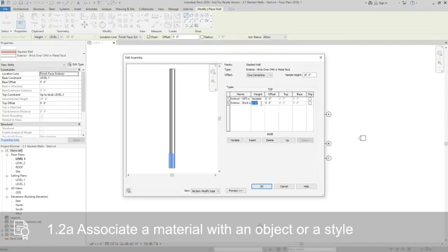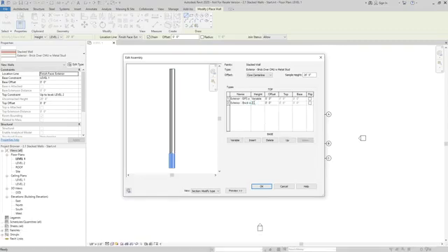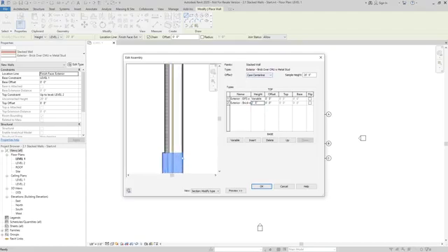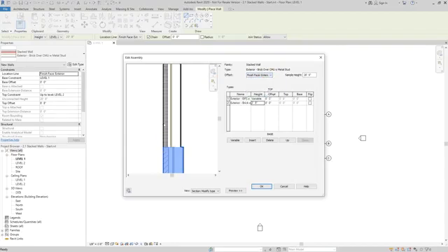For our base, we're going to set this to 2'8". And our offset, which is going to allow us to align the walls into different locations, we're going to set to finish face interior, because we want to make sure that this interior face is always aligned. The way the two walls align, we're given pretty much our basic location line settings here. So if I were to change it to something like finish face exterior, you can see now it's going to align the exterior face but leave a jog on the interior. We're going to leave it at finish face interior.